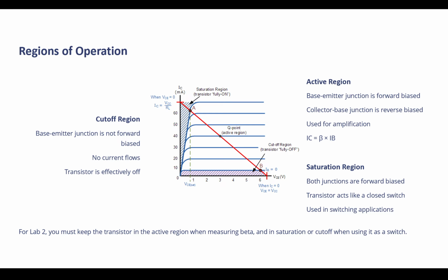Before in MOSFET, we said the gate is isolated, so we apply a voltage to create an electrical field. In BJT, the control pin is directly connected to the semiconductor. That means when you have a voltage, you are going to have a current. In MOSFET, that wasn't the case because it was isolated. Here, you will have a current if you apply any type of voltage.